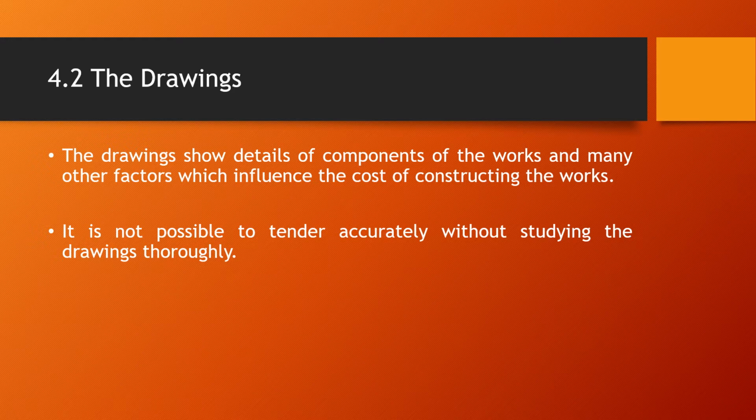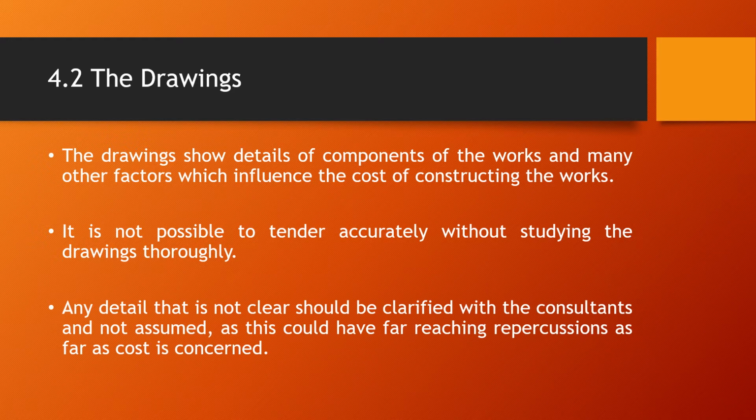I would not have included that because I would not have known, because I haven't seen the actual drawings. So it's very important to study the drawings, to see the details on the drawings, because if you miss anything on the drawing, that could really cost you at the end. So if there's anything that's not clear on the actual drawings themselves, it's always best to give the consultant a ring and inquire rather than assume that this is what he meant, because an assumption can be very expensive at the end.